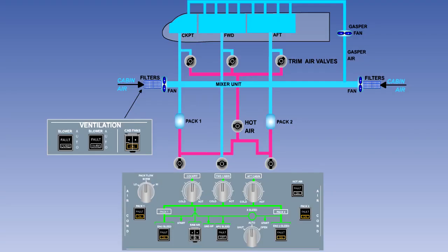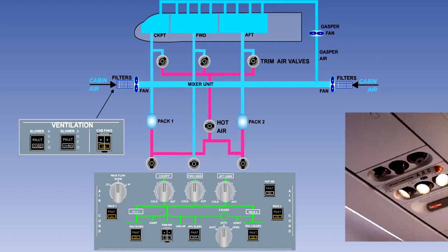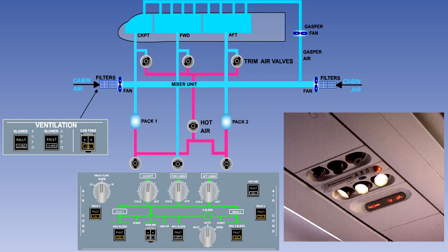The ducting is in 2 distinct sections, to provide for separate flows of cold and heated air. The cold conditioned air is supplied to the passengers individually, through a system known as the Gasper air system. Gasper air is tapped from one of the zone's supply ducts upstream of where trim air is added. The Gasper fan provides a positive supply of conditioned air to all zones through individually controlled outlets or punkah louvers.